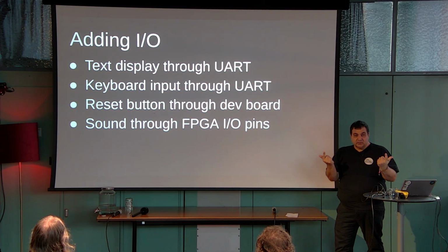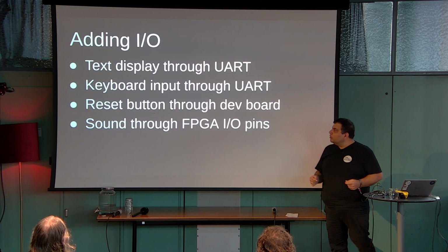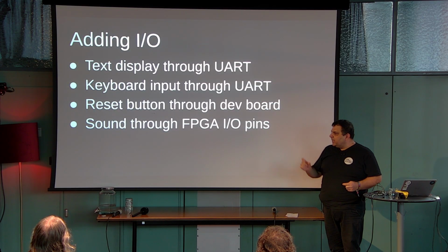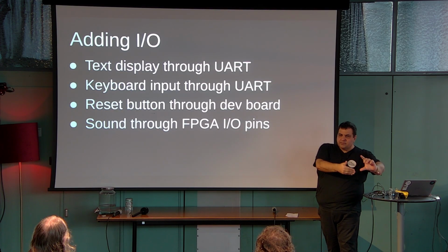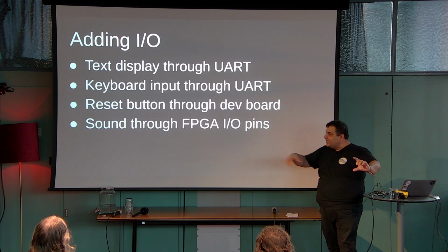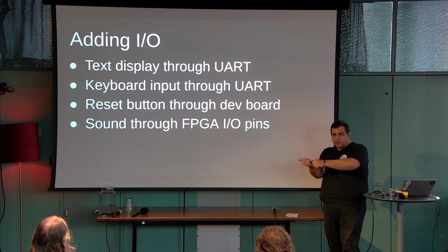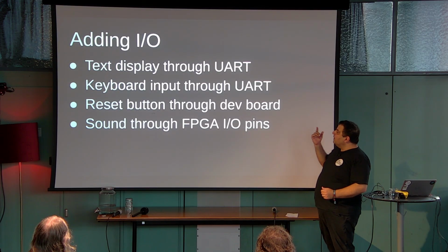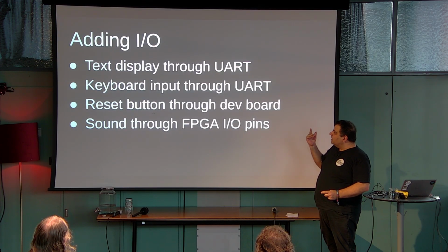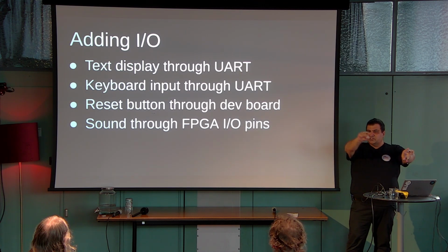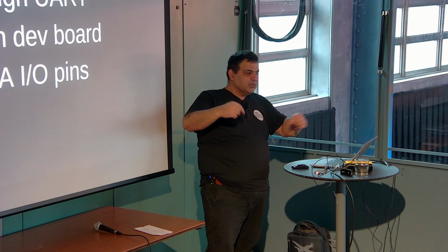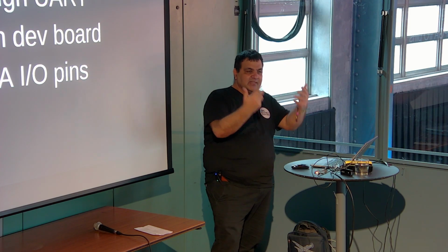We have UART. So what we can do is add a hardware component that 60 times a second scans the memory area between 400 and 800 and dumps it to UART. And then we can take anything that arrives from the UART and expose it at C000, which is where the Apple II exposes the ASCII of the last key pressed.